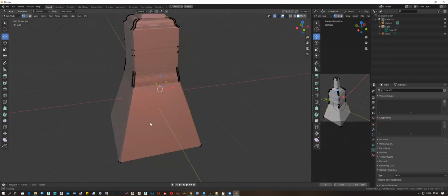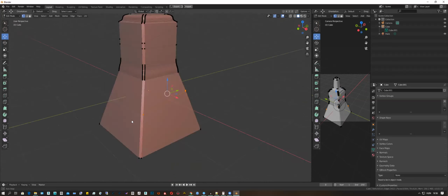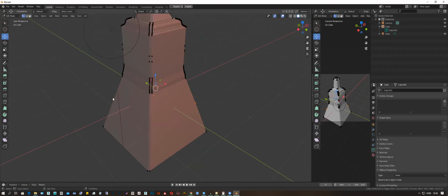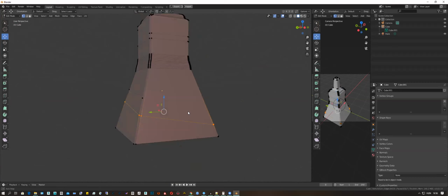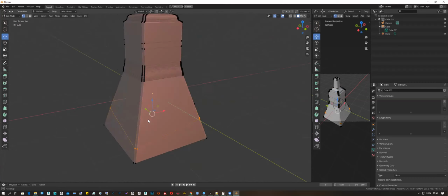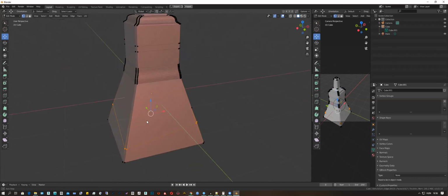However, as you see, it's not working like loop cuts. It's not cutting through. But there is a solution for that also, because if you press the key and click up here, press Z and press C, space, and it's cut through. Basically, the Z key is helping you to cut all the way through.